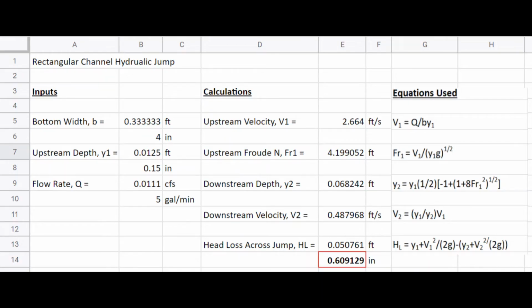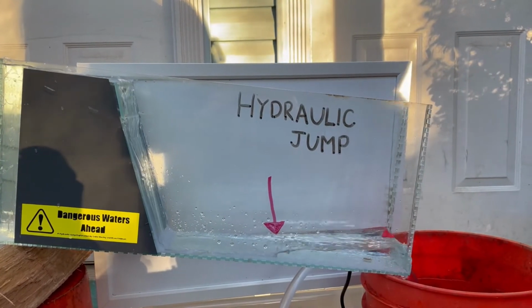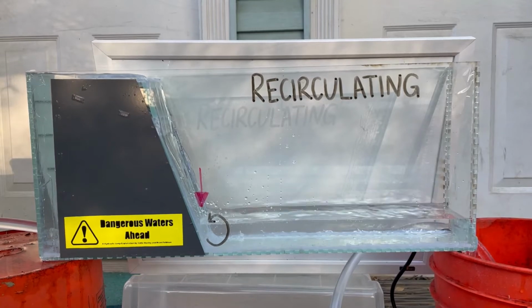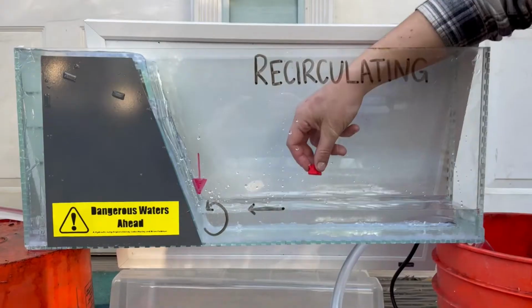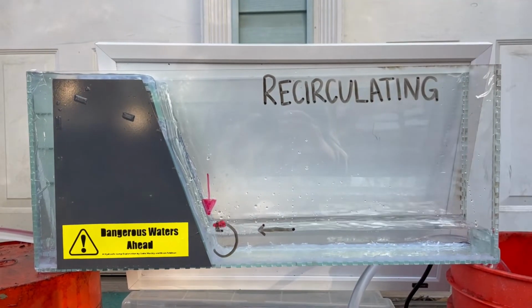Sending a small kayak down the river shows that while the paddler may fall out of his kayak, he is washed downriver. As we change the angle of the channel, the dynamics of the flow changes. This is now a recirculating hole, which we predicted due to where the supercritical flow meets the subcritical flow, indicated by the red arrow. As the kayaker falls down the stream, he is sucked back into the recirculating hole. Even dropping him into the water downstream, he can be sucked back up into the hole.